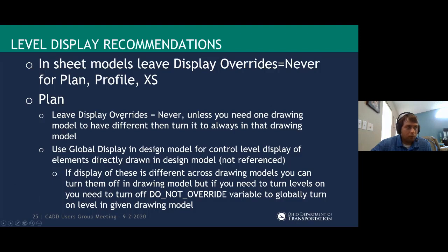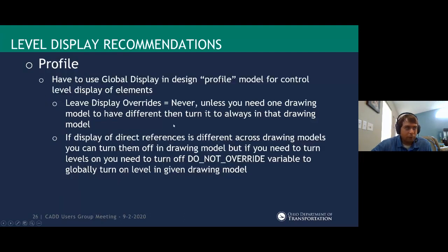Pretty much plan view, use display override, set to never until you need that one-off change, and then use global display for those direct references. For profile, you pretty much have to use global display for everything, as you saw. But again, use that display override just like in plan view. But if you need one to be different, switch it off of it.